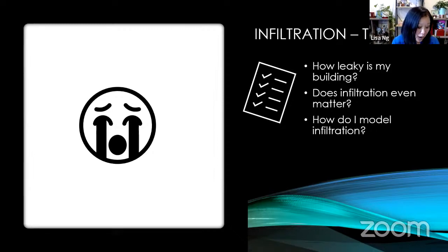And so I'll point you all to a paper I wrote in 2018 looking at the effects of using what I'll show you later to incorporate HVAC and weather into the simulations. And we showed that building envelope air tightness has a better energy savings when you use building airflow physics rather than the same value for both buildings.